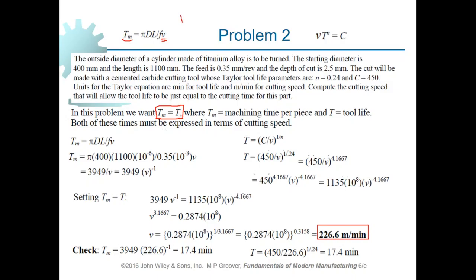However, the value of V, cutting speed, is acceptable within a range. There is a minimum and maximum value for cutting speed if we take a look at the handbooks. So it is only acceptable as long as cutting speed is within the acceptable range and not outside it. Okay, any more questions?